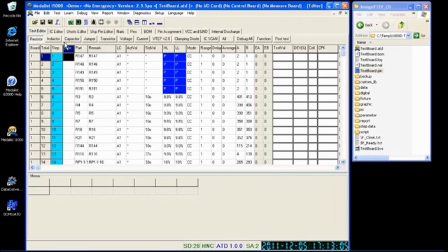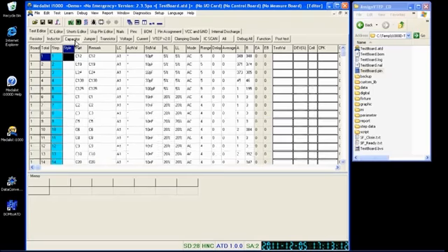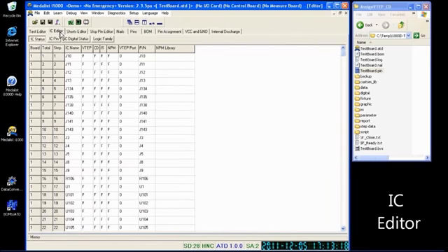The test editor interface shows you all the different types of tests that you have in your ATD file. So you have the resistors, the inductors, and so on and so forth. What we're going to do now is go straight into the IC Editor tab over here. Under the IC Editor, you'll see 4 buttons: the IC Status, IC Pin, IC Digital Status, and the Logic Family. For the VTEP assignment and clamping diode assignment, we only need to work with the IC Status right now.